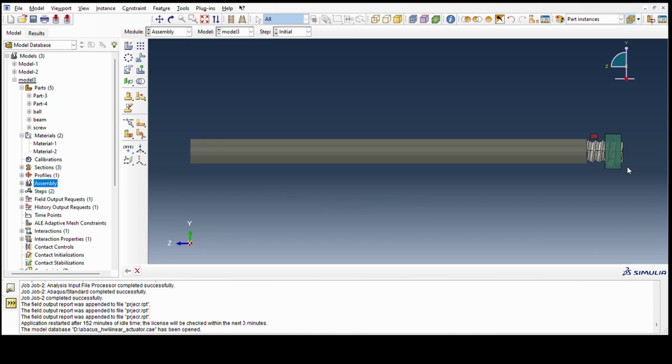So the final assembly looks like this. The 25 mm part is made of the screw, and the rest of it is made by the beam element. There was a correction to the radius and the length of the beam element, as I equated the moment of inertia of the screw and the beam, as well as the max deflection caused by the screw and beam when they are loaded in a cantilever way. With that, I was able to calculate the radius and length of the beam that I need to use here to have the same equivalent screw.